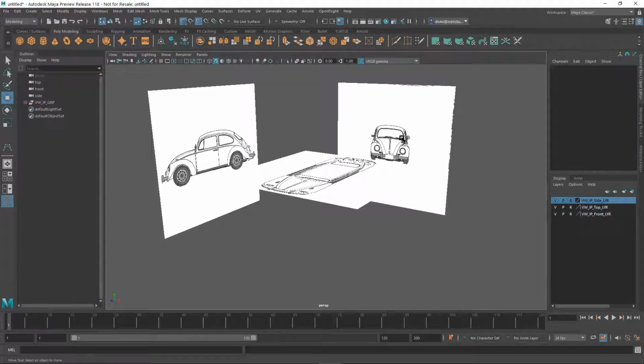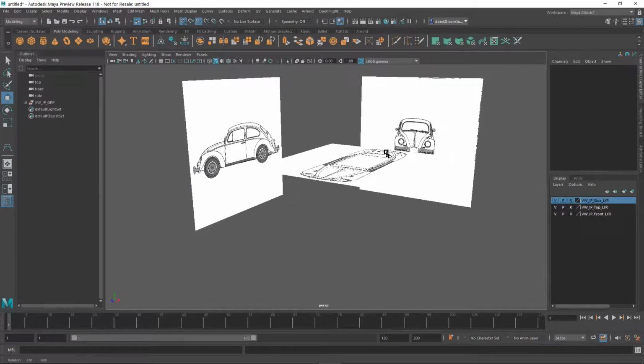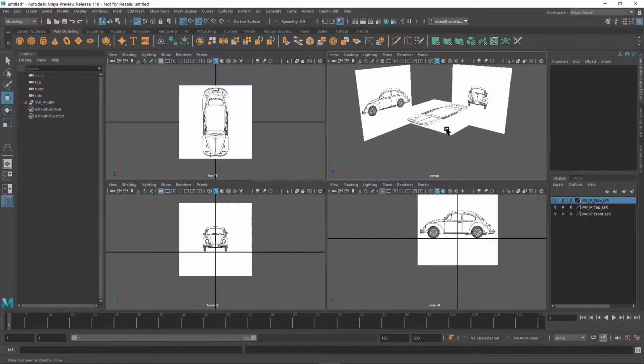Now you can make it bigger. You can make it 2000 by 2000 if you want more resolution, if you're doing really tight detailing. But 1000 by 1000 is usually good enough for basic stuff. Okay, so now the thing is, everything came in the middle, but the middle of everything is about here. So I have this now too high. So now I need to access just that plane there and move it down to this plane here.